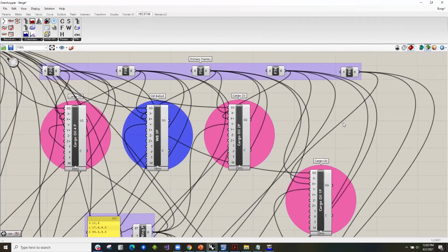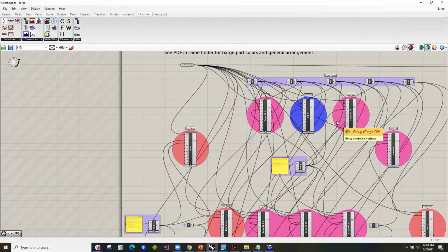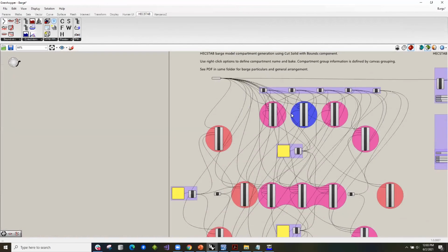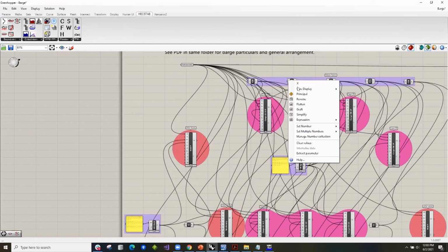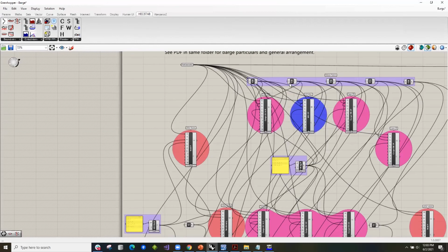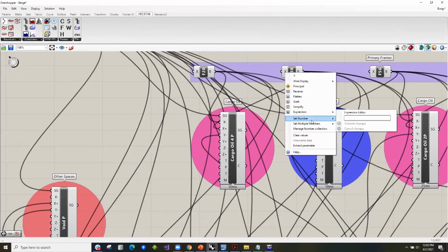And depending on how you lay out the Grasshopper, if you're building the Grasshopper with the intention of designing, you're not quite exactly sure, maybe the hull isn't set yet, or maybe bulkheads aren't quite where you wanted them to be. I can, for example, move bulkheads around quite easily if I just change the input value on this one bulkhead to whatever I want. So if I flip that to some other number, it's right now at 21.8.